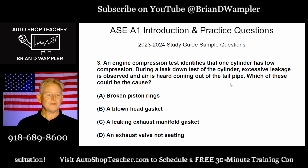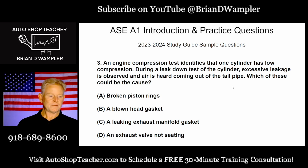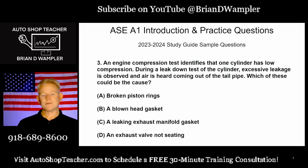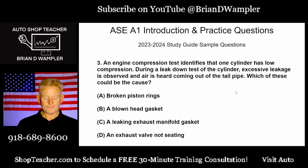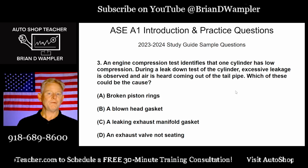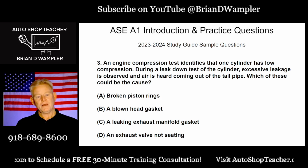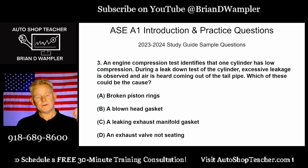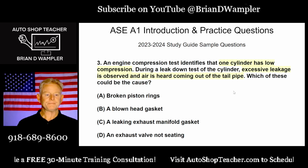Which of these could be the cause? Broken piston rings, a blown head gasket, a leaking exhaust manifold gasket, or an exhaust valve not sealing. I already told you very briefly what the test is doing, blowing air into the cylinder. The piston should be at top dead center and all of the valves closed. All right, do you have your answer?